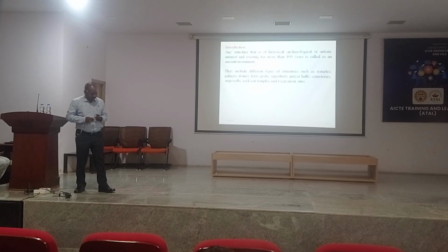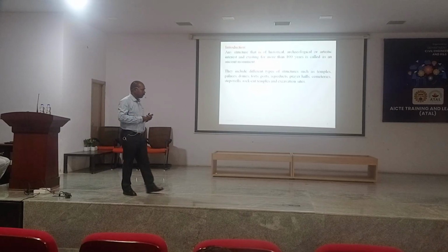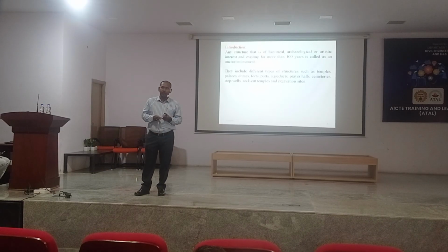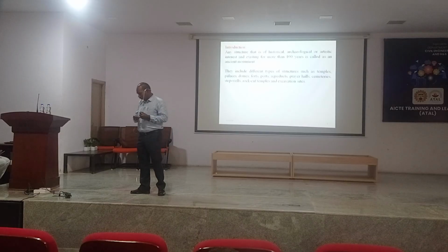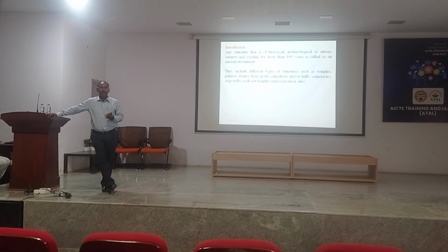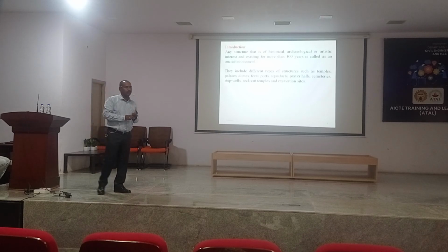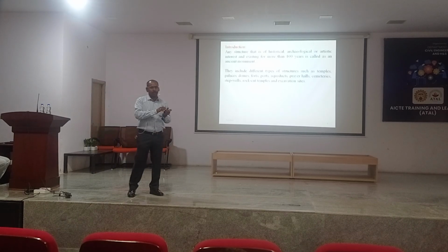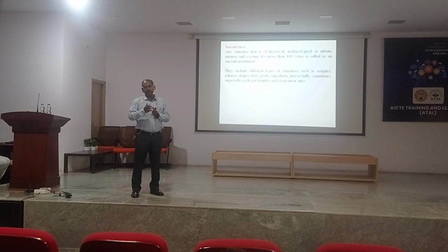In Warangal, one temple was recently recognized by UNESCO, the Ramappa temple. Our students did research on the Ramappa temple. They found out what material was used in those days, the characteristics of this mortar, and developed a similar material which can be used for repair applications of the Ramappa temple.